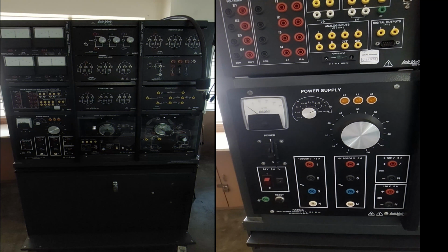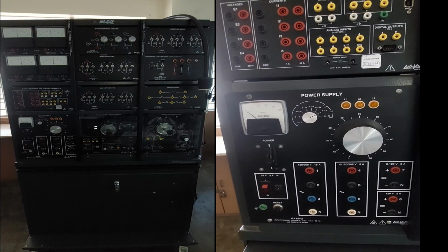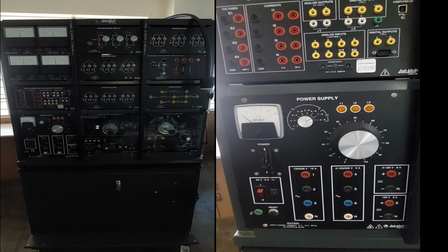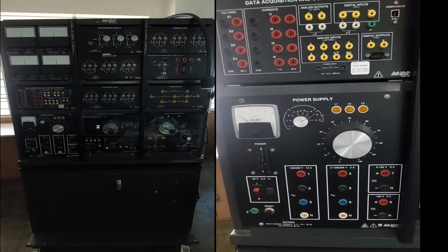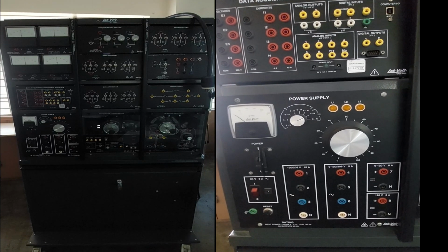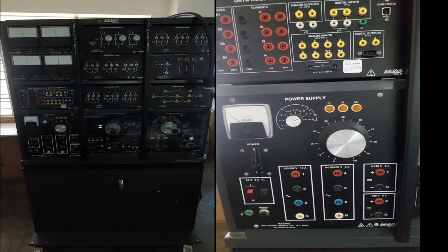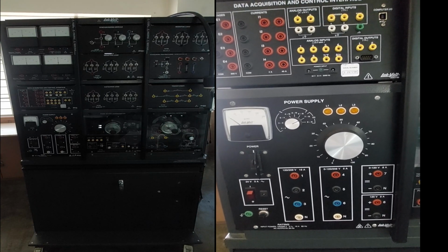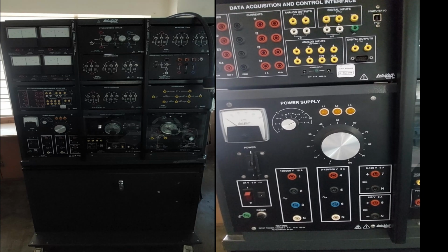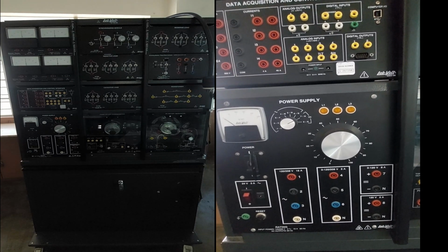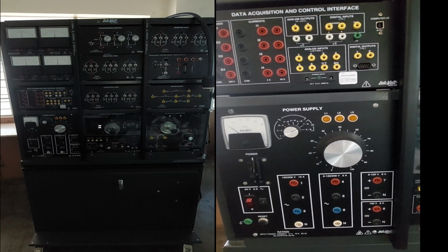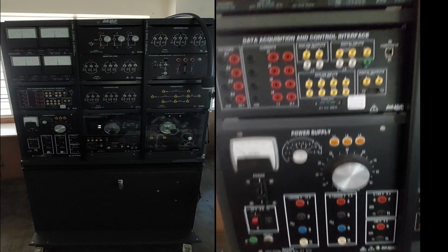The devices that will be used in the experiment begin with the power supply. The power supply will be used to energize the circuit from 0 to 120 volts. This terminal of the power supply is at terminal 7N. This will allow us to control the voltage from 0 to 100% of the capacity of the supply voltage. This will also supply the 24 volts that is needed by our data acquisition and control interface.